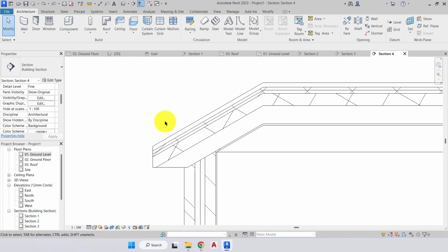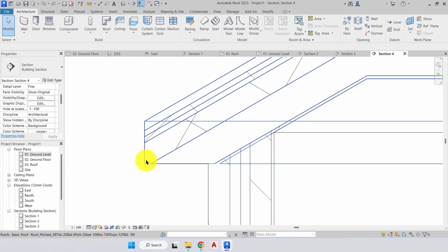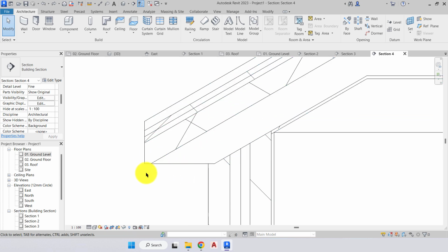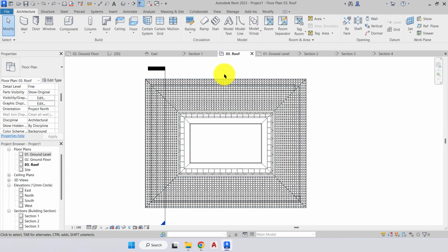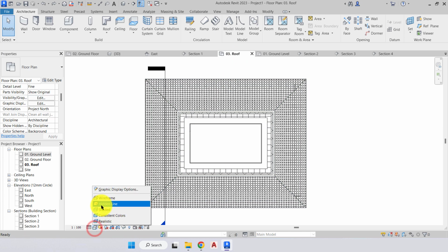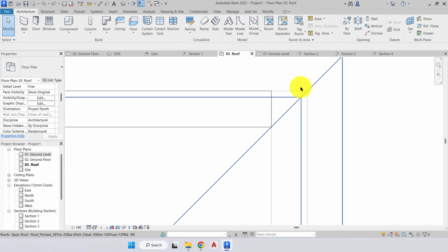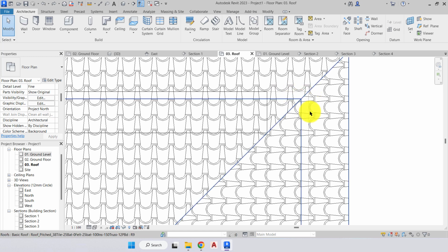And so now we're going to create our soffit board, which will sit underneath our roof, and it will close off this area for us. It will protect our truss and our insulation, and from that, we can also attach our guttering. So we'll go to our roof level. First thing we'll do is change over to wireframe so we're able to see the edge of our external wall.